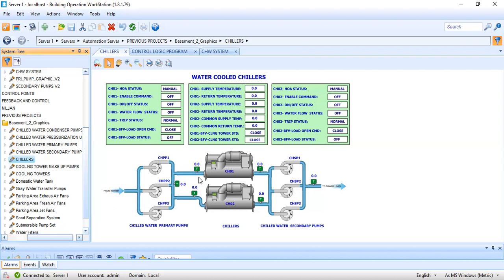So, butterfly valve with valve actuators. When the chiller is working, those four valves will be open. Then the secondary pump's job is to suck that chilled water, then put it to the building load.